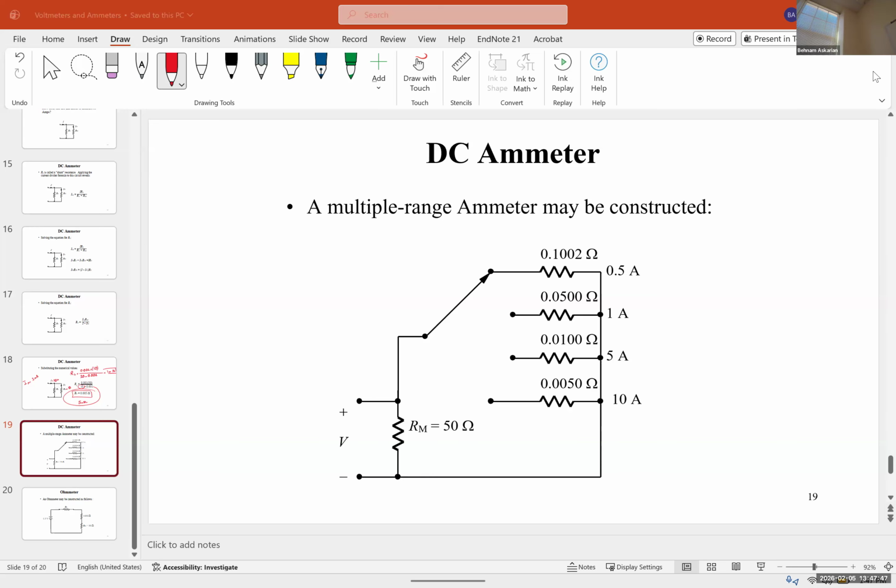Now, newer generation digital multimeters have an automatic system. They take a sample of the current, and if it's too much, they automatically adjust the resistor. But with older ones, you have to use a knob. The ones that you saw in the lab, on the table, don't require adjusting the knob. But if the current is above a certain level, you have to change the terminal, because that automatically connects it to a different resistor. Some of them have multiple terminals because after a certain voltage, it's considered high voltage or high current, and you have to switch those terminals.